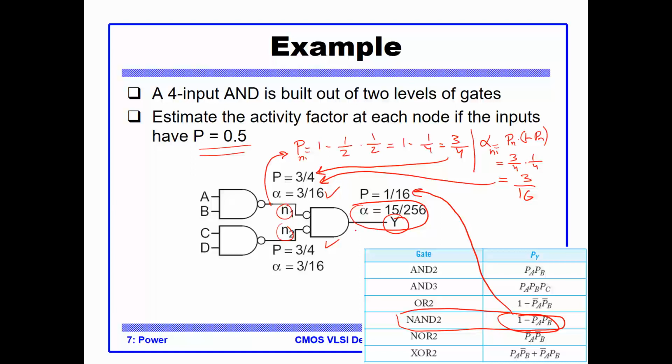Well, the activities should point out to me, when I do power analysis, where those nodes are that consume most of the power, and typically they are the most active nodes. And the most active nodes are the ones that I need to study and examine, and think about how I can make those nodes quieter if I could. And there are techniques to make those nodes quieter.